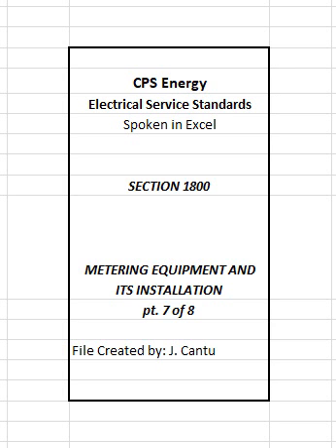All conduit nipples on CPS Energy meter sockets and enclosures shall be rigid metal conduit, RMC, or intermediate metal conduit, IMC, and provide effective bonding in accordance with the NEC and Section 1700-1809.